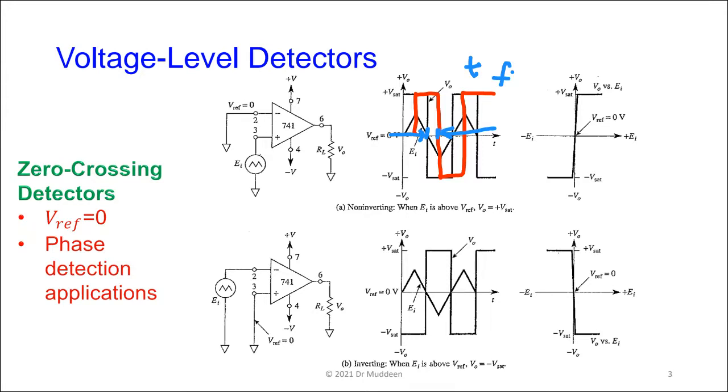The saturation values, now I just mentioned the saturation value, V out here. V out is a generic voltage value, but V out, sorry, wait a minute. The question was, is this the same as V out? Yes, correct. You remember the V out, this here. This is what we're measuring here. So V out is going to go between plus VSAT and minus VSAT. What it's not going to do is go between plus V and minus V. All right? Fair enough? Yeah? Nice.